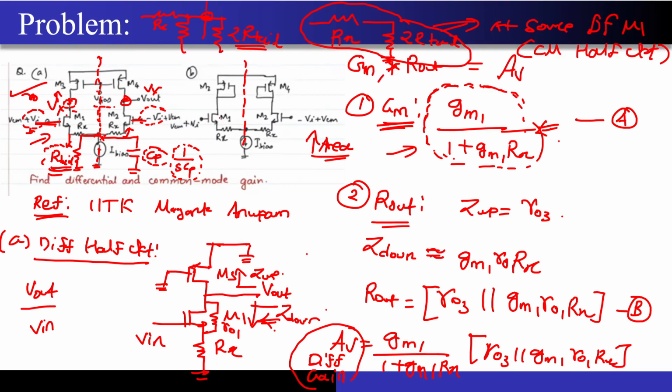And note, these transistors are not operating at RF frequencies, correct. We are talking about baseband circuits. So when do you need the minimum channel length that is available in the technology? You generally need it to design RF circuits, correct. So if I give you 180 nanometer technology, it does not necessarily mean that you will choose the channel length of these MOSFETs as 180 nanometer. Generally, to make sure that you get a high enough output impedance, that is R0, and a good matching between M1 and M2, you should generally take 3 or 4x of L-min, that is 540 or even 720 nanometer of channel length, correct.